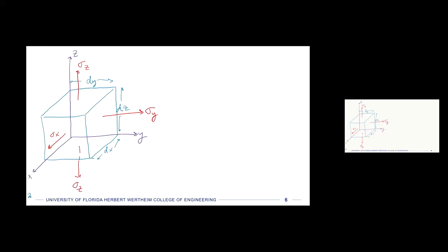The shear stresses are easy to get mixed up, so we'll have a specific convention to describe those. And so we're going to call shear stress tau. So we'll have tau ij. And we'll have 2 subscripts for all the shear stresses. The first one is the direction of the plane, or the normal to that plane, on which it acts. Okay?